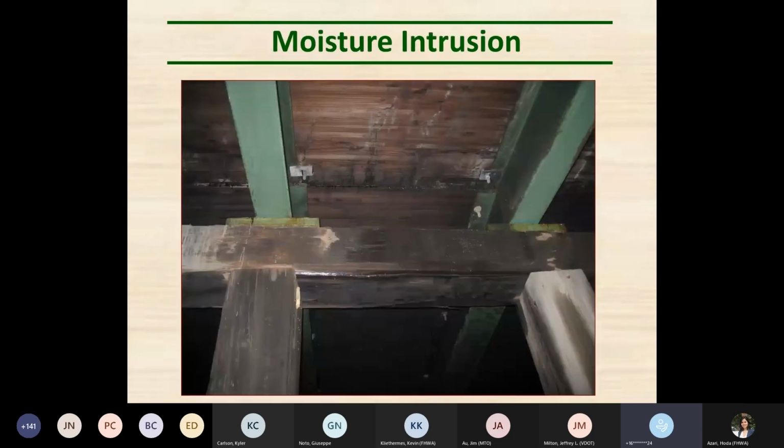And you can see here, I talked about water intrusion. The day that we were there, we could visibly see water falling from the crack between the panels, which was directly aligned above the cap member. And remember, the bridge is an arched roadway, so those panels at the joint almost funneled water into them if the asphalt cracked, and then it deposited it right on the cap member underneath, leading to some corrosion on the steel, but also deteriorating the cap beam member. So again, the county made a decision to replace the frame member.